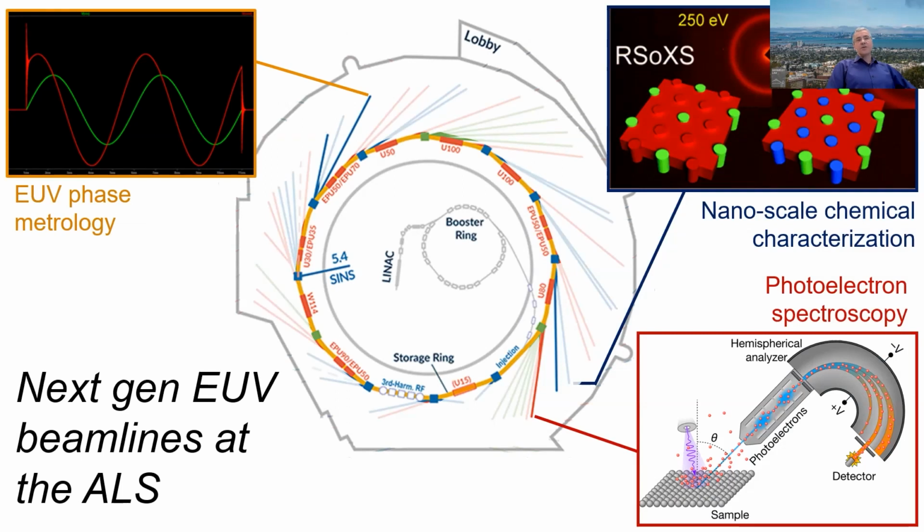And these are focused really on fundamental materials characterization. So on the mask, instead of just using the mask to absorb or let the light transmit, we're now going to use the mask to actually control the time delay of the light. And doing that, you can get additional imaging capabilities from your lithography system.